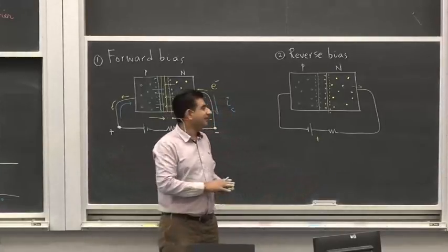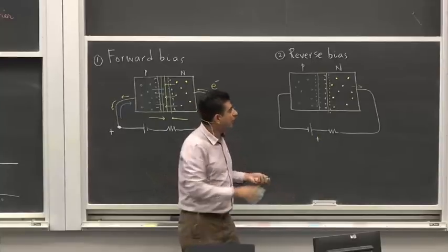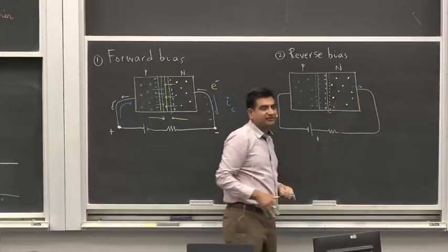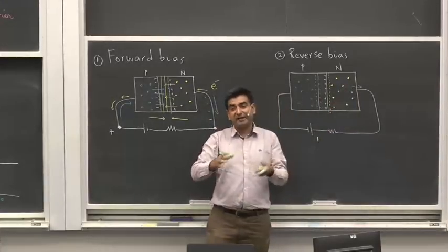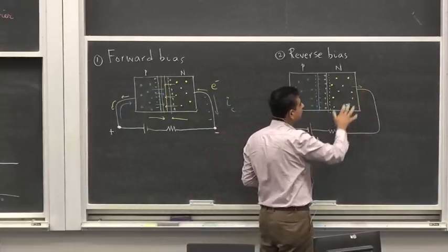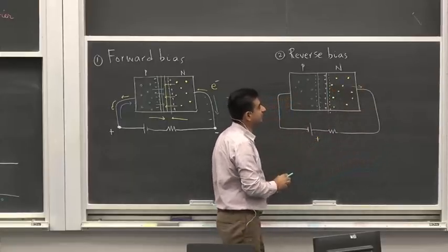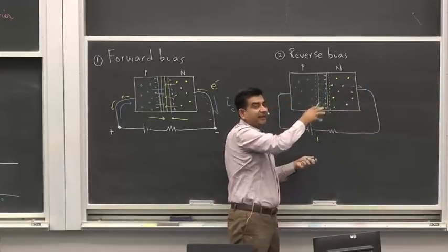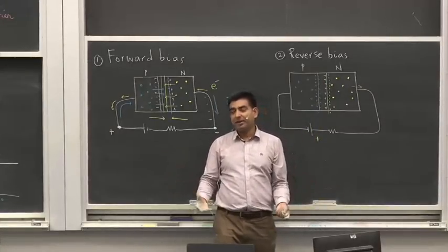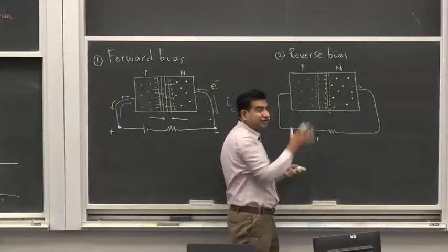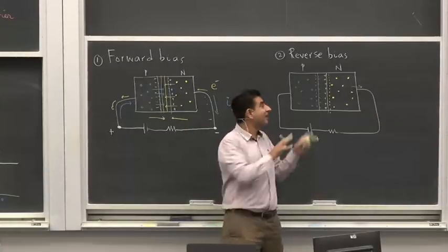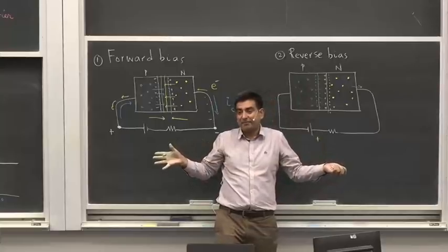Okay? And this process immediately stops because there is no charge drift across the junction. In order for current to flow through the external circuit, you have to recombine electrons and holes. It's not possible that you're supplying electrons into this circuit and supplying holes into the system or drawing electrons out from the system. Electrons and holes cannot just pile up inside the diode. They have to recombine. But they only recombine inside this region. Now this region is bigger in size and there is no drift of electrons and holes into this interface, so conduction doesn't happen.